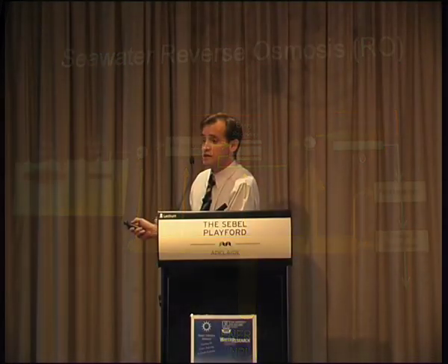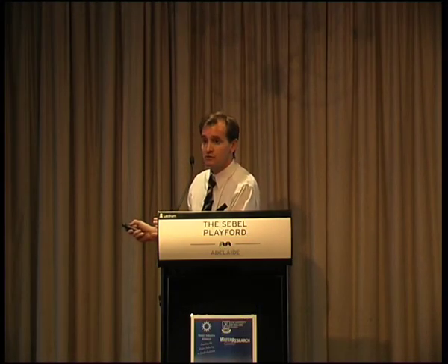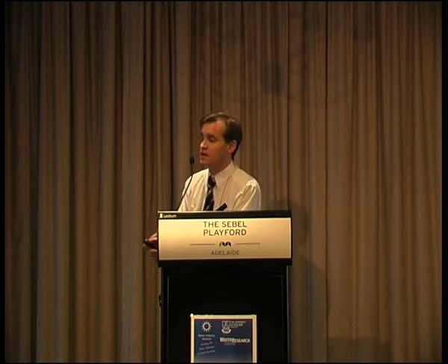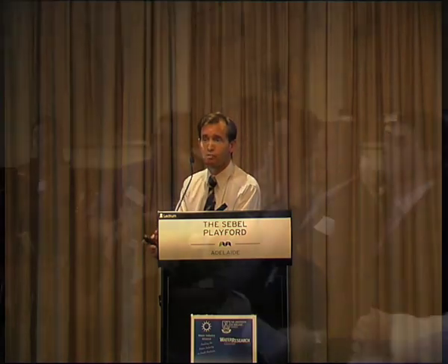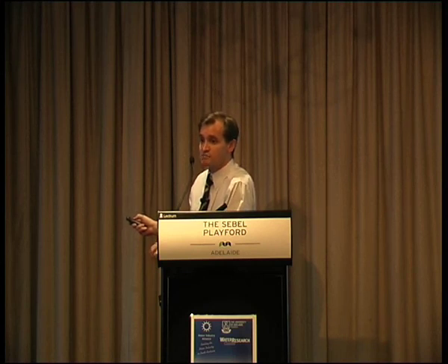As you take the seawater and remove pure water from it, the seawater will concentrate and increase in concentration. In a modern seawater RO plant, it will have a recovery of about 50%. And what this means is that as you pass the seawater through the reverse osmosis plant, the concentration will increase from 35 grams per litre up to about 70 grams per litre. To achieve that, you need to pressurise the seawater to about 70 bar, again to overcome that natural tendency for osmosis to occur. After you concentrate the seawater, it becomes a brine that needs to be disposed of.